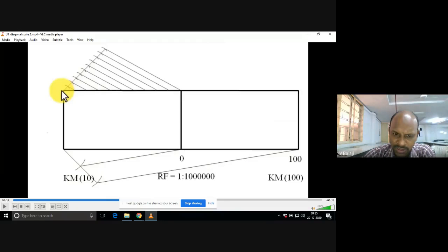Now let us do like this. Now remember here, see, any angular line we have taken, 10 equal arcs we have drawn, and the last arc I have to join to the 0 line. Okay, and match your mini drafter scale to this line. Draw parallel lines to that line. So all lines are parallel to each other. Automatically the first part is divided into 10 equal parts.